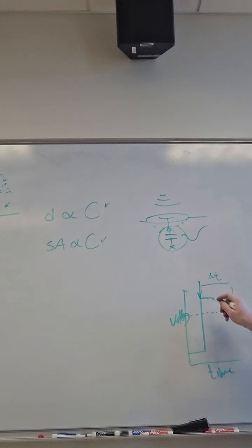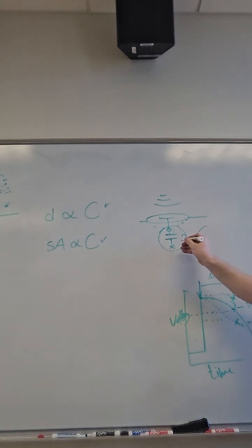And the interesting thing is that if there's more capacitance, it won't decay quite as much, so it will be this much higher. If there's less capacitance when we check in at that time, we'll have decayed more quickly, and we might be all the way down here. Okay, so that is the voltage change when we check in. If we check in here, it might be like 4.2 volts. If we check in here, it might be 3.8 volts, so on and so forth. Okay, so that's how we can turn a capacitance into a voltage. We're testing the discharge rate of that capacitor in order to then understand the capacitance of it.